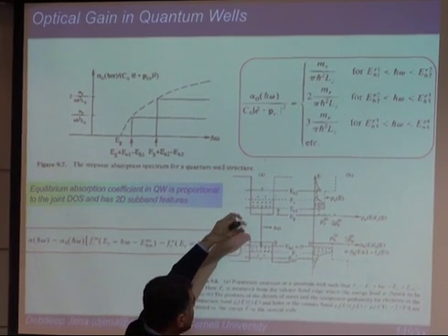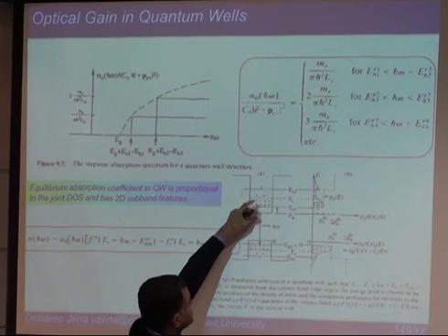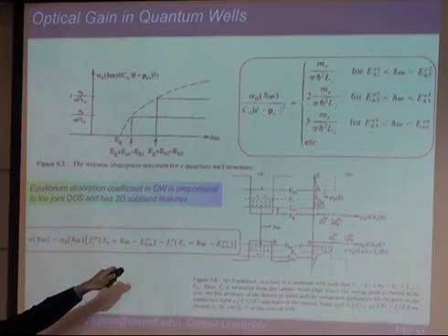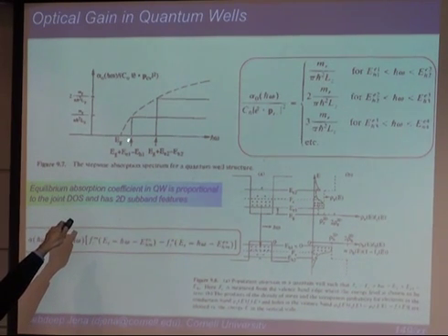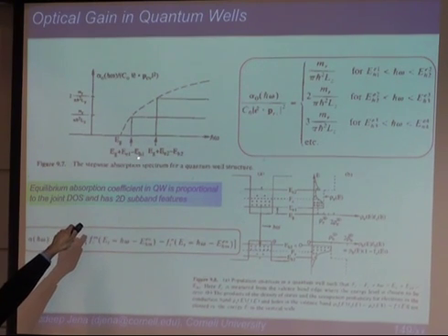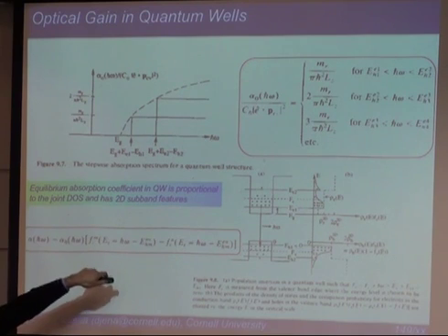Right? So it's the bulk band gap of the quantum well plus this is the minimum energy, the smallest energy photon that can be emitted from here. And so that's where this edge occurs: Eg plus E of the electron quantum level, and it's written as minus hole. You understand what it is. The signs, you can fix it.